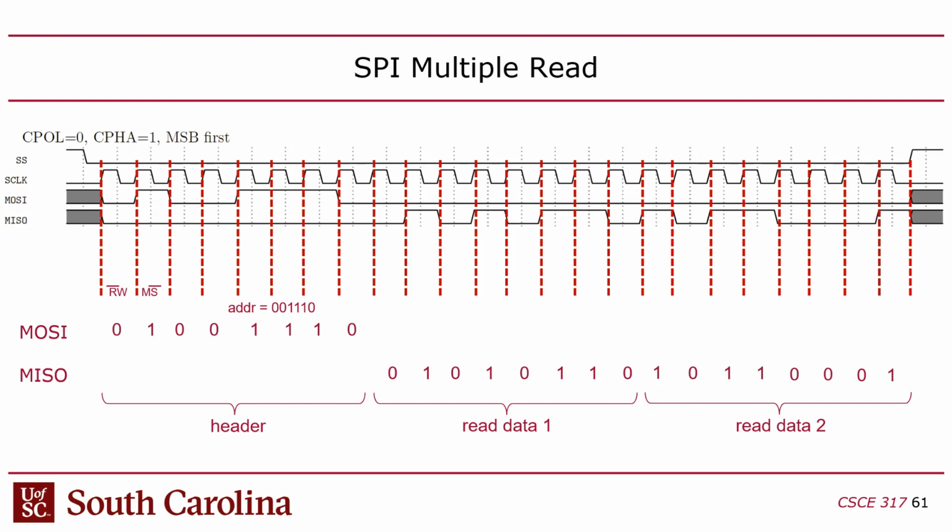But that's pretty simple. So in the first lab that I'll assign this week, we just want you to write a C program or Python, your choice, that will read a text file with these transactions, like a trace of these waveforms, a text representation of this waveform, and that will decode the transaction, what it's doing. Some more recent oscilloscopes will do this, where you read the data and it decodes the transactions for you. It'll tell you what the exchanges are, what's happening there. But you can obviously write software to do that, which is what the first lab will be.